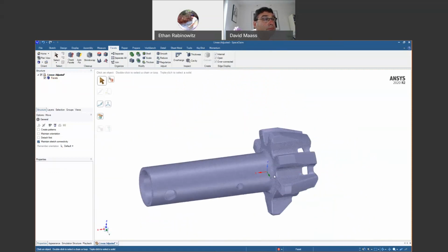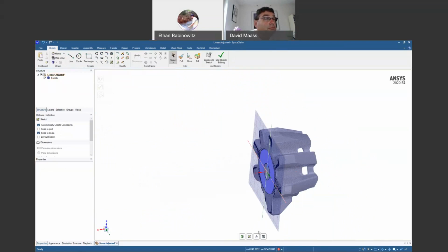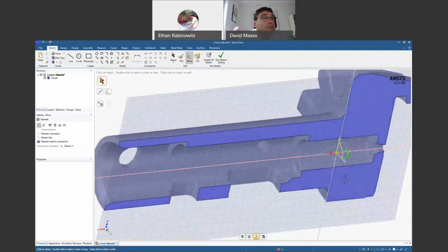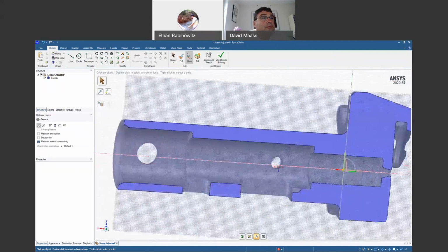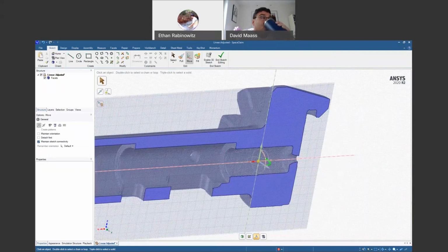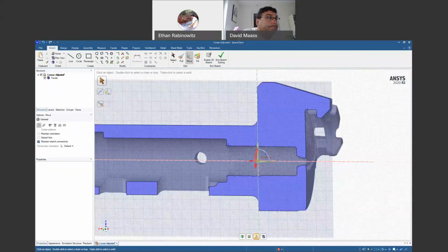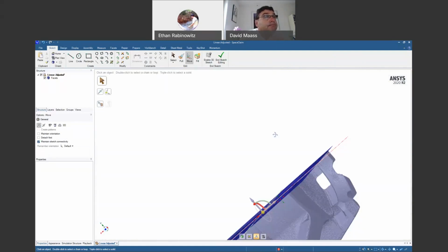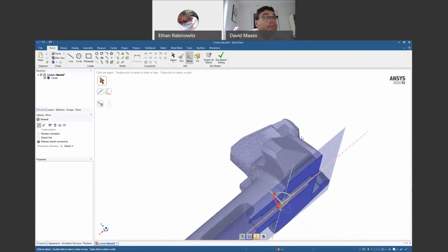So let's grab, and we are recording, just verifying that. So we'll grab our x-axis, go into a sketch, use a keyboard shortcut, and we'll just take that sketch and rotate it this way. Technically, we don't need a good profile on the top and the bottom. We really just need a good profile on the top to do our revolve. And so if I want to capture the part of the head between these, I think the best place to do that is probably out over here.